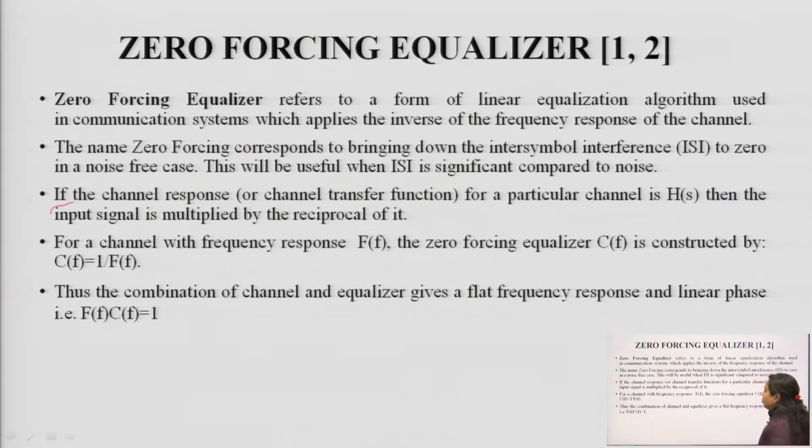So, zero forcing equalizer. A zero forcing equalizer refers to a form of linear equalization algorithm that is used in communication systems, which applies the inverse of the frequency response of the channel. The name zero forcing corresponds to bringing down the intersymbol interference, ISI, to 0 in a noise-free case. This will be useful when ISI is significant compared to the noise.